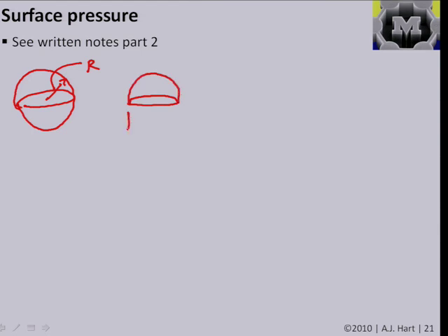and because we cut it, like mechanical engineers, we want to draw a free body diagram. And so we're going to say that around the line, around the perimeter of the sphere, we have a surface tension which we're going to call gamma, which has units of force per length. And then if we sum the total force around that line, that would be F gamma is equal to just the distance, 2 pi r, the circumference, multiplied by gamma.